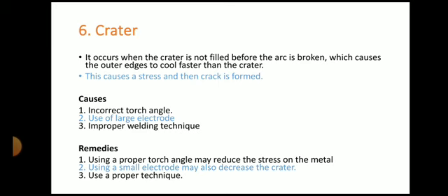The sixth external defect is crater. It occurs when the crater is not filled before the arc is broken, which causes the outer edge to cool faster than the crater. This causes stress and a crack is formed.